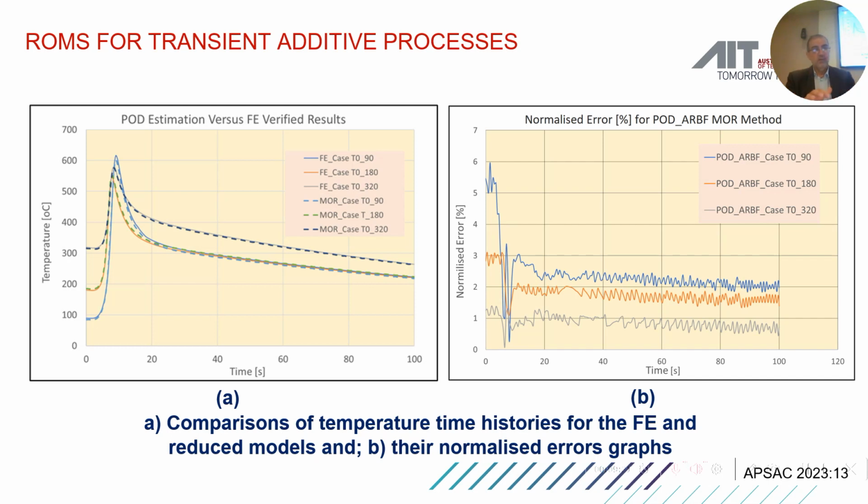What we've done here is we ran some finite element analysis and generated the builder. Then we ran another set of finite element analysis, which we call DOE, design of experiments. So the builder, the real-time model, didn't know about the new cases. Then we compared the new finite element results with the reduced real-time model, and that's the results you see almost fitting on top of each other.